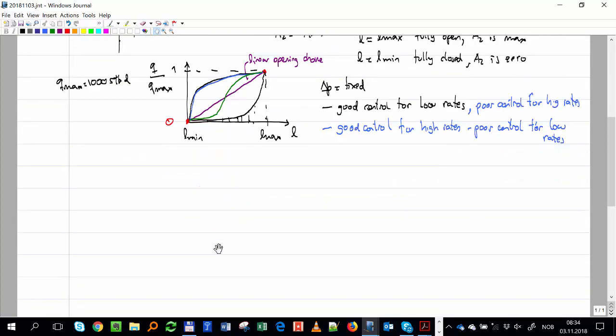And now let's go for the gas, which was the challenging part and the exercise we're going to do here. So the choke equation for gas, and we depart from the same equation, dP plus density U dU equals 0. And then this density is a function of pressure, so we have to put it together with pressure.